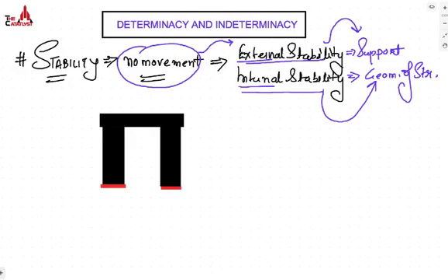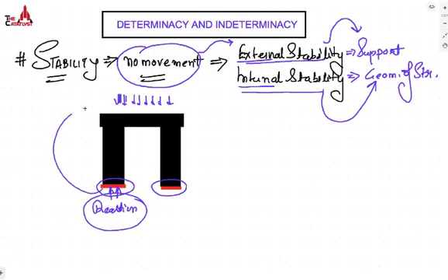It means that when the load is acting over this structure, then due to that load, there can be movement of this structure. But these supports will develop an opposite reaction in order to resist the effect of these external forces which are acting. The support will develop the same type of reaction as the force acting. If you try to rotate the structure, then the reaction developed on this particular support will be a moment. It means that externally the body is being prevented against any type of movement with the help of the reactions which are developed at the support only.